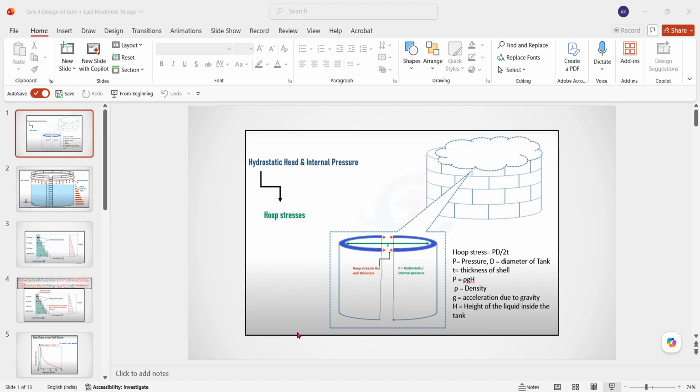And as this tapers, manufacturing of a tapered shell plate is not possible. So this is the additional extra thickness, which is not required, but we cannot do anything. We have to select the lowest thickness plate, and the hatched portion is the required thickness. Course 2, course 3, course 4 differ, as a single plate of a high height or width is not possible. So from the market you have to purchase the standard widths available. That's why the different courses will come.